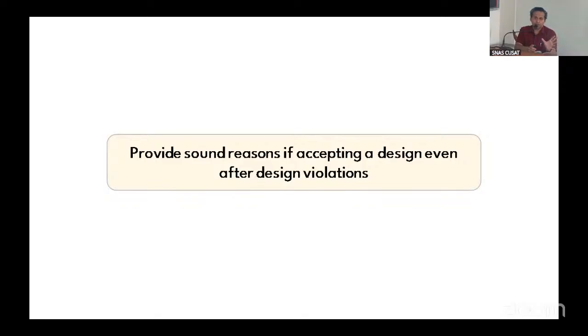And in a lot of cases in engineering analysis, what you look at is the boundary conditions. In the analysis, boundary conditions are fixed. In reality, it's not really going to be fixed. There's going to be a little bit of give and take out there. So you need to understand that there might be a little bit of leeway, and you need to take that into account.